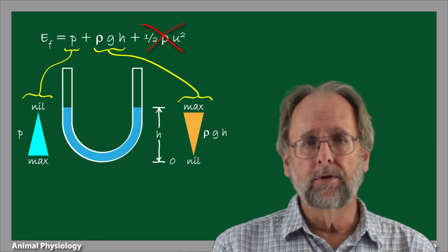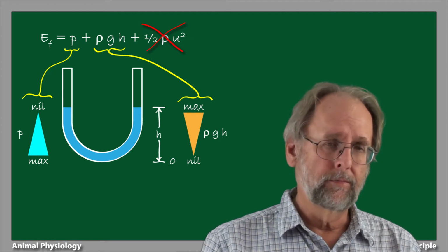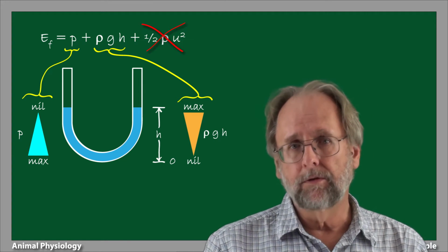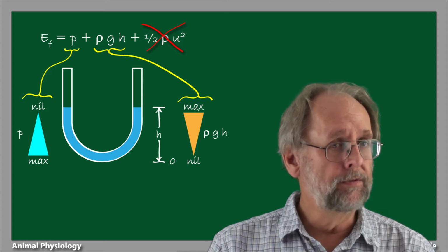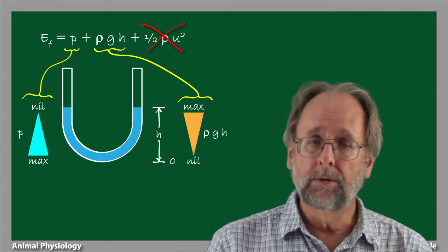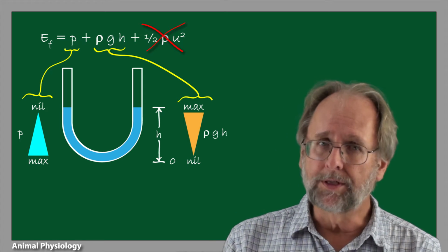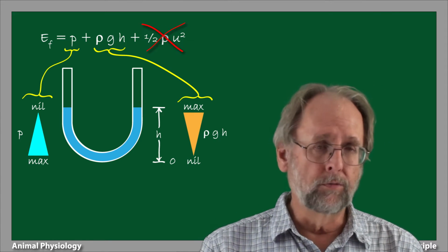Here I want to digress for a moment to make an ancillary point. The assertion is often made that fluids always flow from regions of high pressure to regions of low pressure. I've made that assertion myself several times, in fact. But we see from Bernoulli's law that this is not always true.